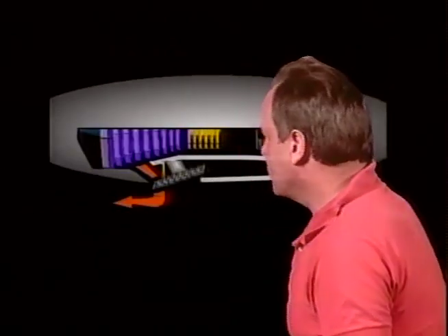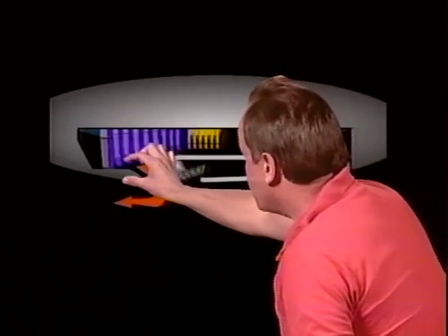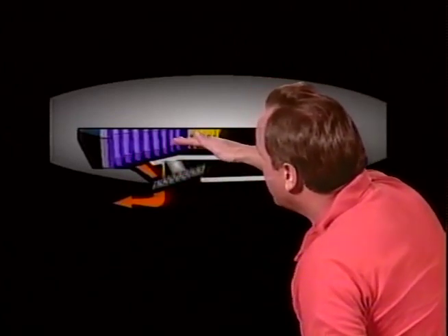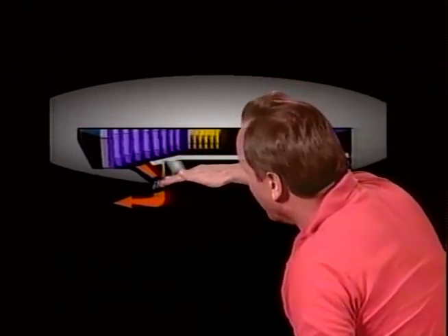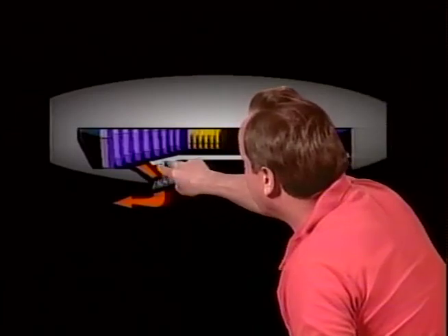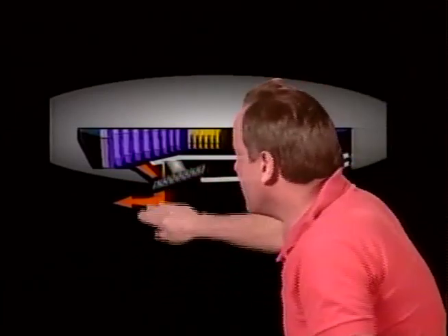Let's take a look at an aerodynamic blockage device as a thrust reverser, and this is the bypass duct on a jet engine. And when you want reverse thrust, these aerodynamic fins move down. They have a little aerodynamic shape to them, and the air comes along and hits those fins, and the aerodynamic shape bends the air and reverses the thrust, and that's an aerodynamic blockage type thrust reverser.